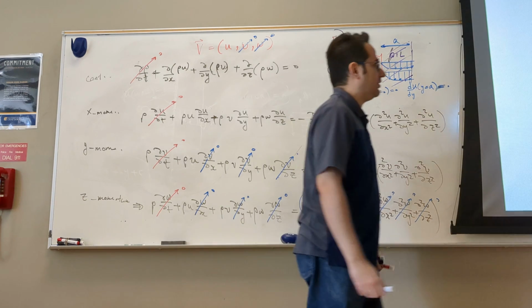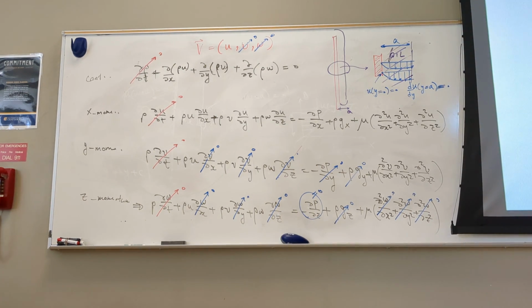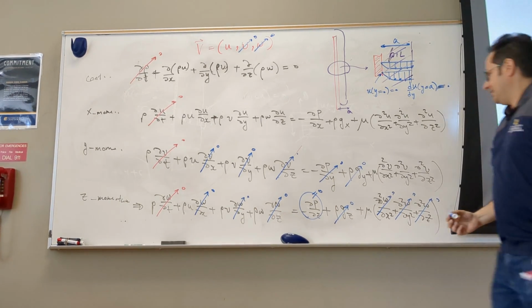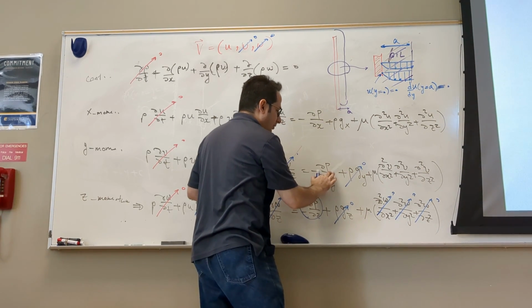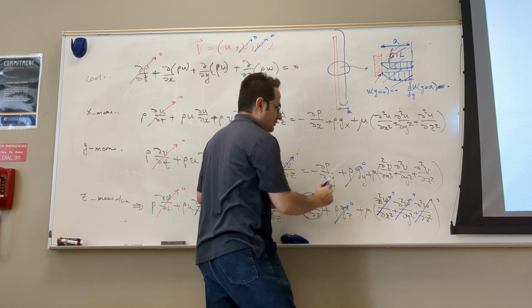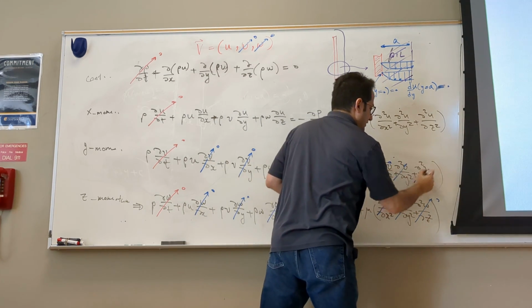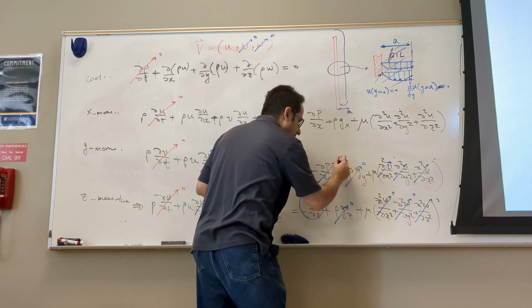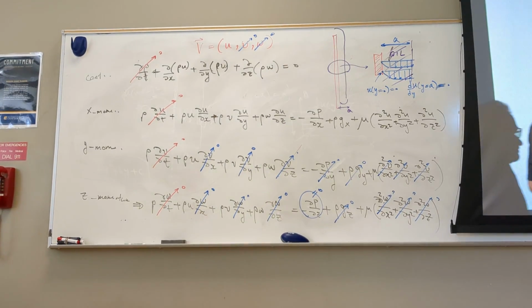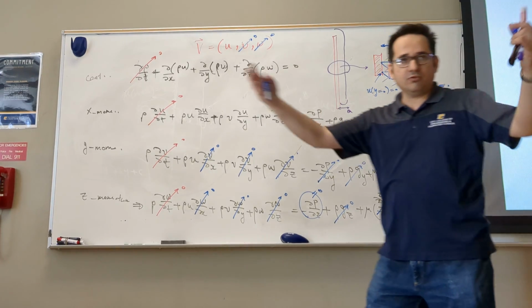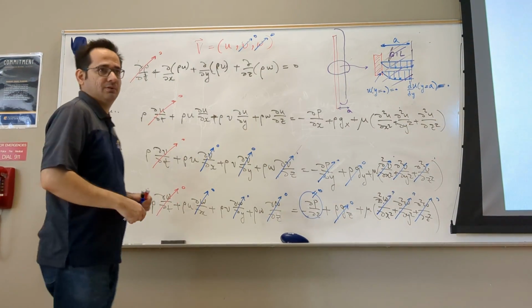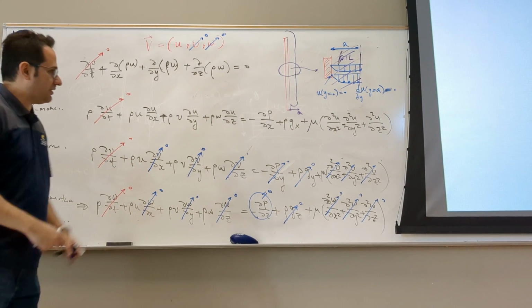So when I say y, I'm talking about this direction. We usually think that y is this direction, right? Make sure you talk about that direction. So zero, and even if you say, well, I don't know about that, you know that this is zero, this is zero, this is zero, then this must be zero. We satisfy the condition that this is exposed to the atmosphere, so the pressure gradient is zero. Why? Pressure is zero. It's exposed to the atmosphere. It's not inside the pipe. So this is the equation I get.